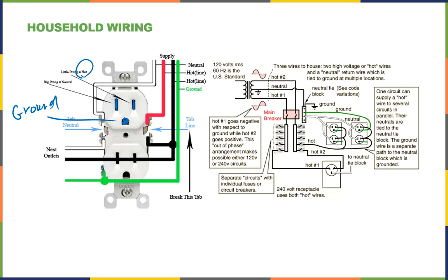The other is you could have a brownout, a situation where you're under voltage. So instead of 110 volts to 120 volts, that's what the range is supposed to be, you might be at 95 volts. And a lot of appliances will be damaged if they're running under voltage. So it is safest to turn them off so you don't risk that damage.